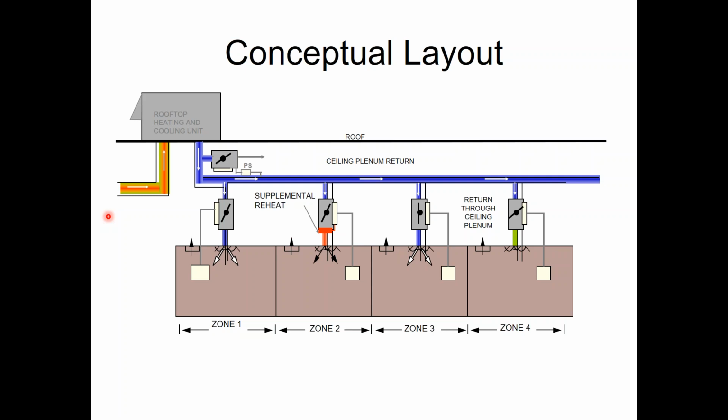So it does become a challenge if you deviate from that 55-degree rule. Most of the guys servicing your building won't realize that and they'll keep changing it back to 55 anyway. The other direction, if you want to go higher, unless you've done something specific with your coil selections, you're probably going to be too high of a wet bulb to do any decent moisture removal. Once you start getting above 60 degrees on a normal feet-per-minute air handler, you're going to have a difficult time reaching the dew point and pulling moisture out of the air. So 55 to 57 degree dry bulb ends up being a nice sweet spot. But you could absolutely design higher or lower if you do lots of other things different from industry standards. And sometimes things are done different.